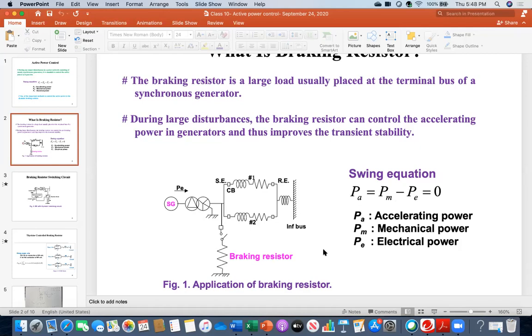So what was the question, Dr. Ali? Can you repeat it? I think you understand the operation of the braking resistor, right? It is designed with a fixed value, a fixed resistance. Just an example, say it has 10 ohm. When the automated switch closes, that 10 ohm is working, and when it disconnects, it is disconnected.